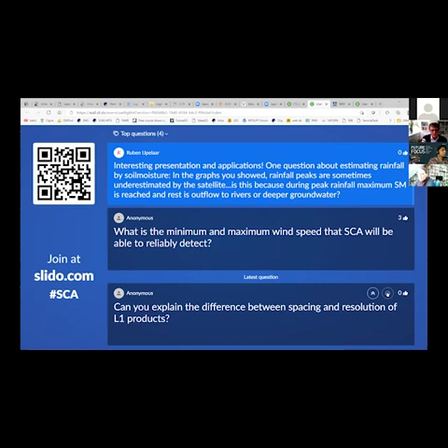And the second problem, as you highlight, is that if the soil is already saturated, soil moisture cannot go up even more. In those cases we go into saturation, and that's why we have underestimation of larger rainfall amounts.